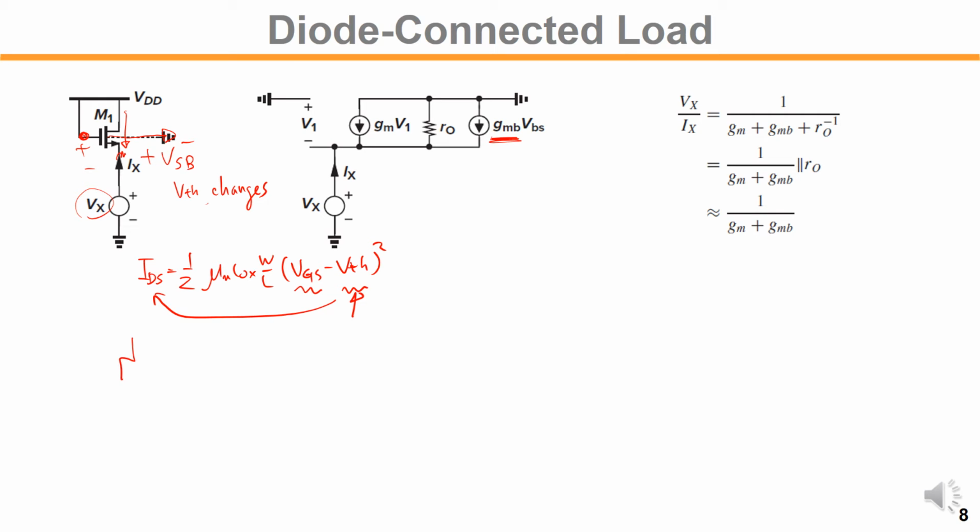So we can model that in small signal analysis using the back-gate transconductance Gmb. In this formation, this is AC ground because VDD is not varying. Now a Vx change will result in what? This is ground. So let's draw that current direction.